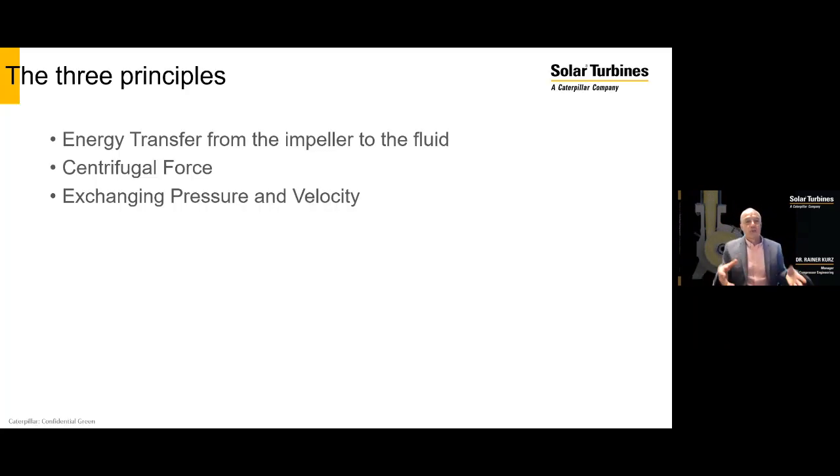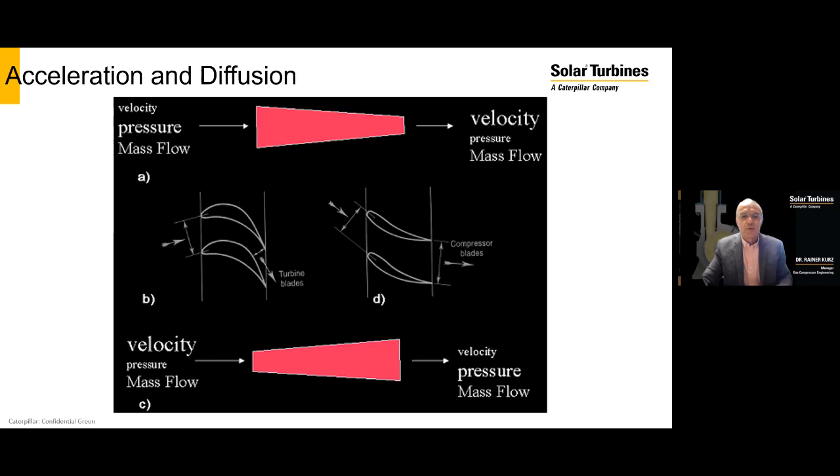On a centrifugal compressor, we actually have to deal with the aerodynamics, and so there are three principles we have to talk about. So essentially the energy transfer from the impeller to the fluid, the use of the centrifugal force, which specifically applies to centrifugal compressors, and then also the fact that you can actually exchange pressure and velocity. So let's start with that one actually first.